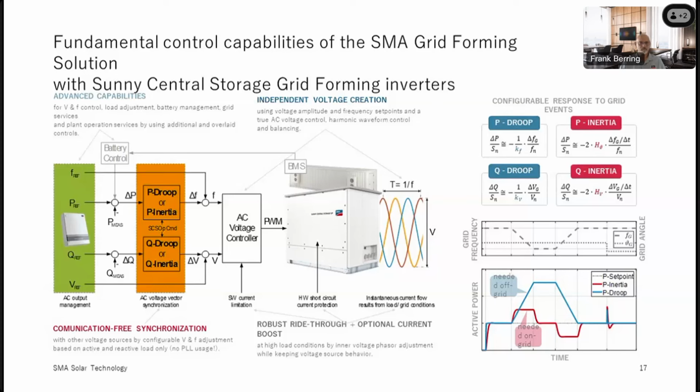For instance, there are requirements in the UK we have seen where for hundreds of milliseconds there's a peak needed for the short circuit in that location. We are seeing other things like in Hawaii, where there's an overcurrent requirement on the POI as well. And I think based on the experience the market in general gains over the years, the adaptation of having at least the boost capability more and more in these project requirements will be established, I believe. So we are already having that in our design considerations. We're giving support not only by sizing, but also by our modeling teams.